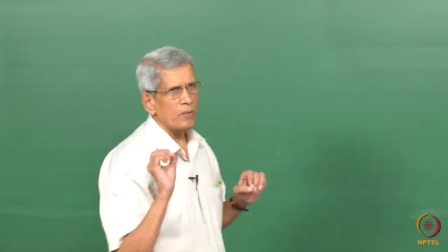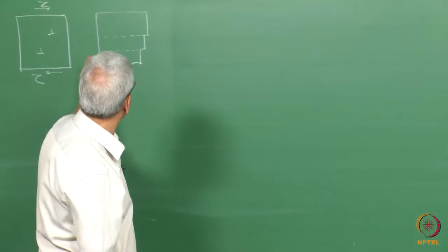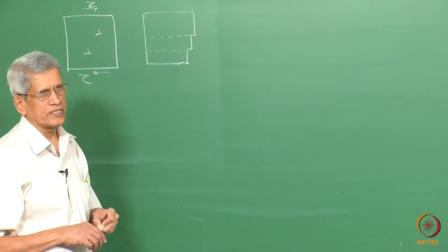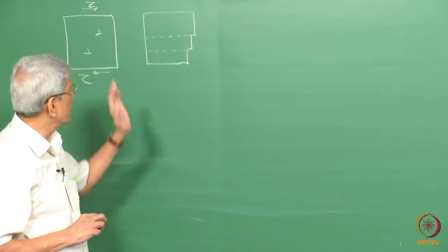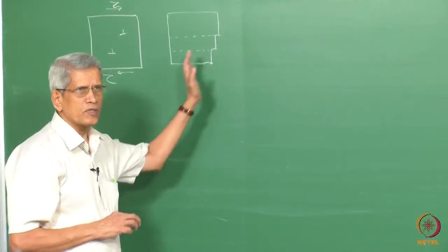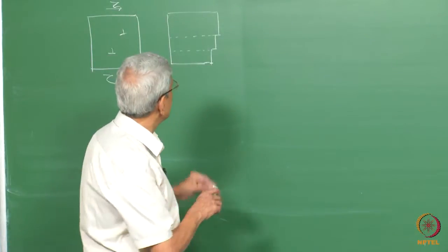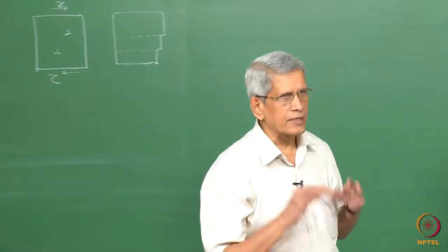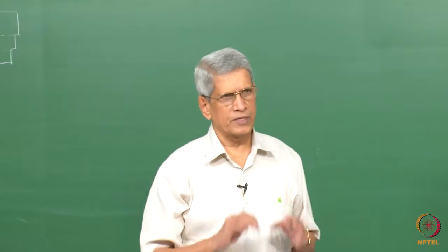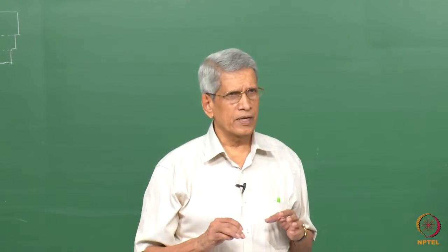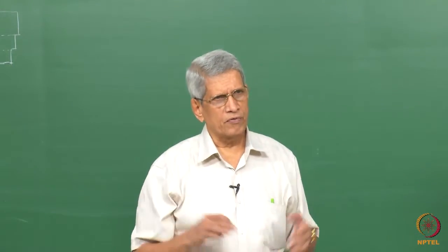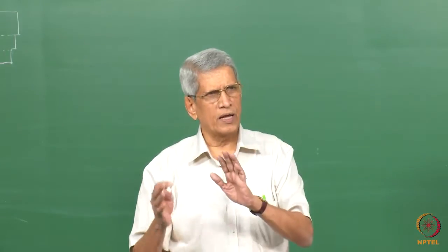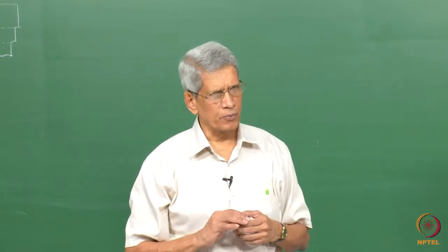That means that the deformation is not homogeneous, but heterogeneous. That is what brings about the shape change, and generally these steps, under normal experimental techniques available for observation of the dislocations or the microstructure, we will not be able to see. Only the overall shape change is visible. That is how we look at it.